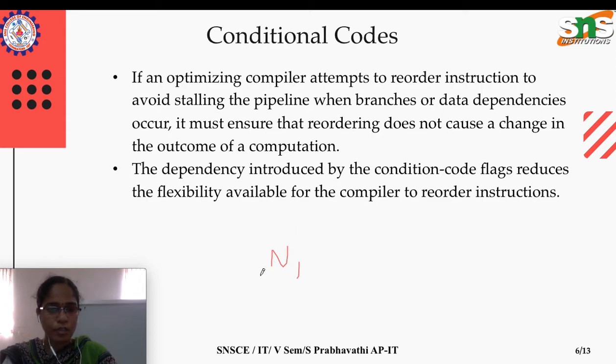If the outcome is a negative value, the flag N will be set in that processor special register, and if the result happens to be all 0, the processor will maintain a bit for storing that in the Z flag. Then whether the addition has an overflow or not, and likewise the carry.